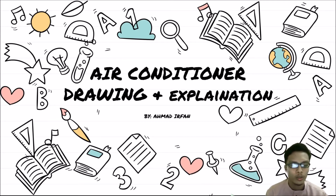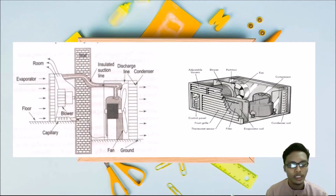Next, I would like to present the air conditioner drawing and explanation. When the system is on, the compressor will compress the gas coolant. The compressed gas coolant will flow to the condenser using a discharge line. The condenser will get rid of heat using a fan, and the heat will go out to the surrounding.